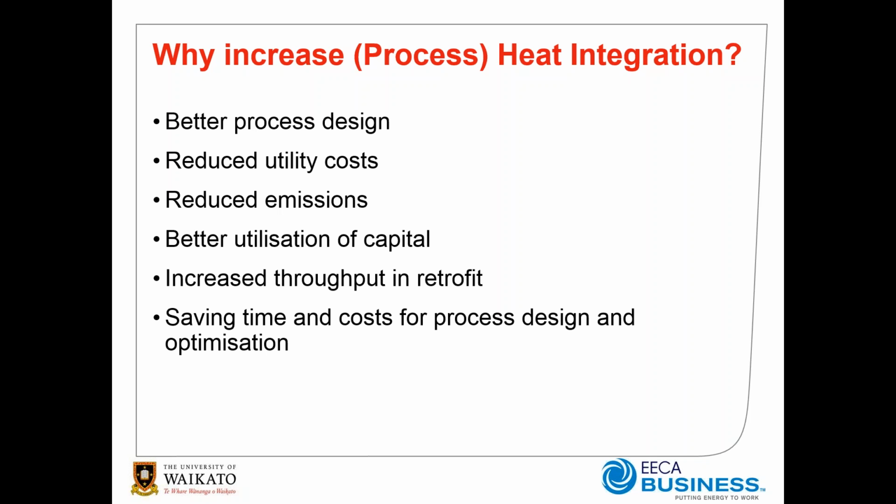We can also retrofit to increase production by freeing up capacity in the heat exchanger network, reducing its energy use, and then freeing up the amount of utility we have available, and therefore being able to increase the amount of production potentially. It can also help us save time in the process design and optimization phases due to the methodologies being very systematic and relatively easy to apply.